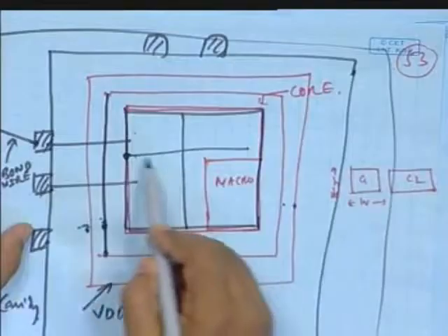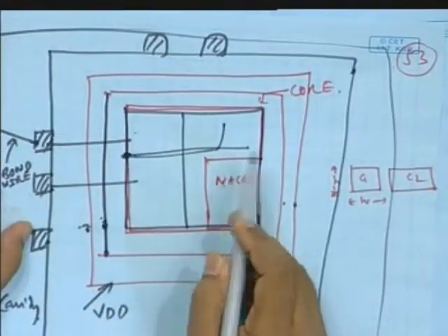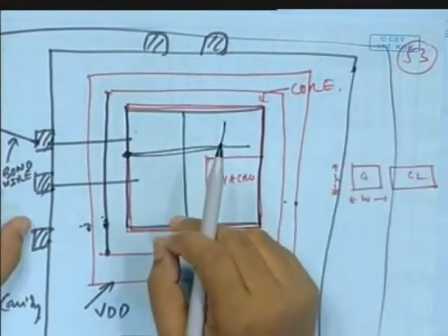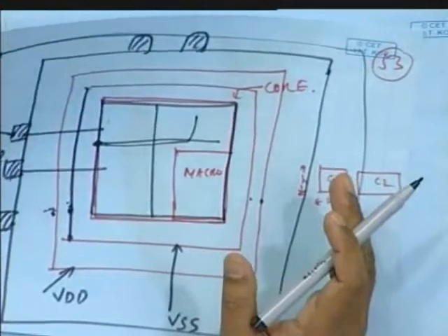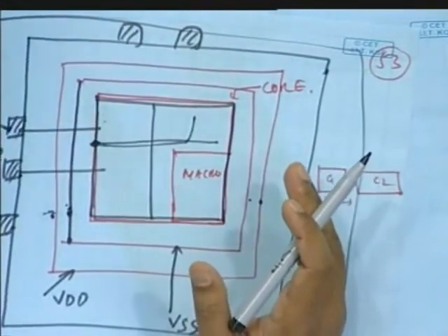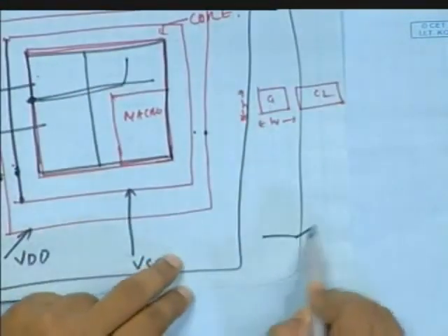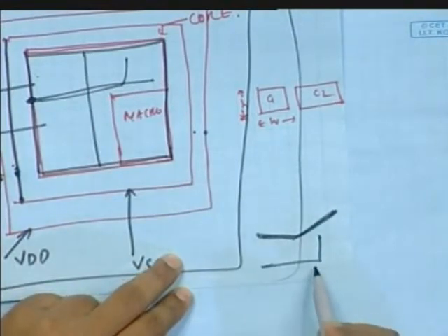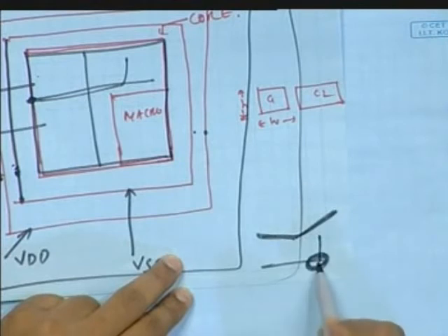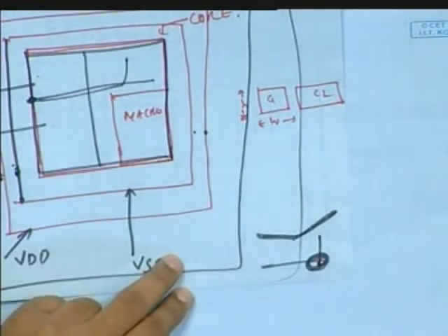These connections, for example, this routing, whether you will be doing 90-degree angle or 45-degree angle, that also matters. There are so many electromagnetic effects. Antenna effects are there. So, for example, if you are connecting like this 45-degree angle or you are moving this 90-degree angle, this is a potential antenna. But definitely the signals are moving and then it's bending, right?